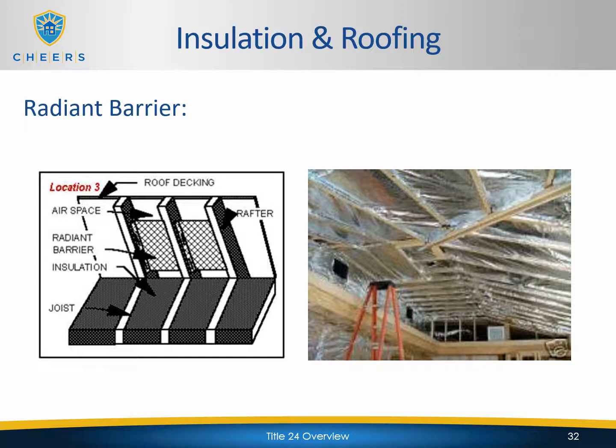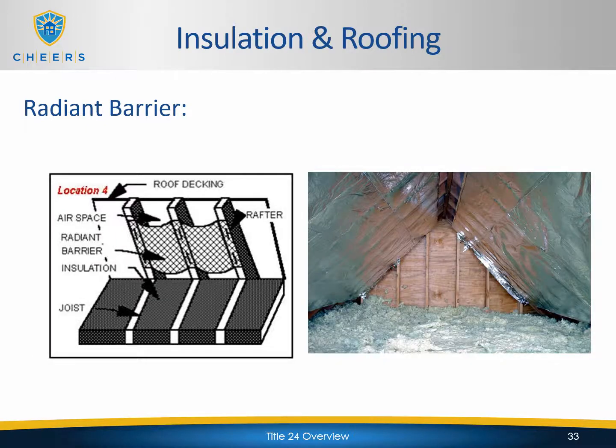They just go back and basically fix pieces of radiant barrier below the actual roof deck around the trusses, and they staple it directly to the framing members. This last application, they rolled the radiant barrier, same type of material, over the inside of the trusses under the roof deck. The one thing that I want to point out on this picture is the fact that the radiant barrier, when prescriptively required, needs to wrap the whole attic. It needs to wrap the whole attic, including gable ends. So in this particular picture, the gable end will also have to be wrapped in order to be compliant.